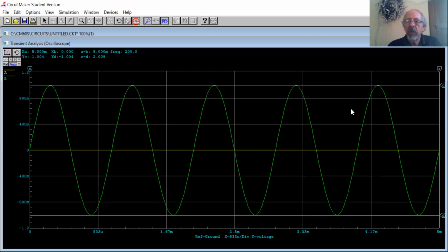So I'm going to cancel on that. Usually what happens is there's a lot of stuff you have to set up under simulation up here to make the thing give you a nice display. So in a lot of the experiments, I will give you the circuits and you just load them up. And I've already set up the simulation so it works correctly. But again, that's for another future topic. So for the time being, this shows you the transient analysis for oscilloscope and certainly the DC. And again, you don't have anything like this in Tinkercad, unfortunately, to allow you to do stuff.